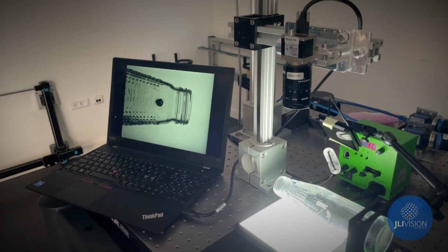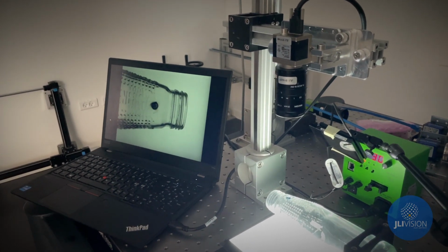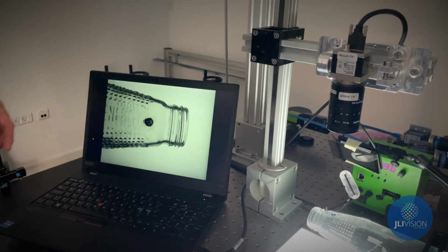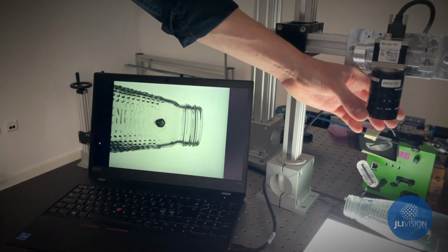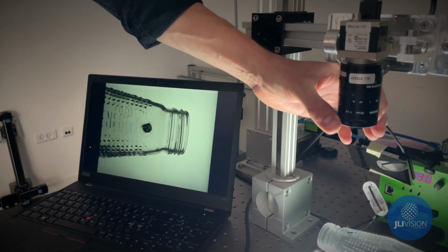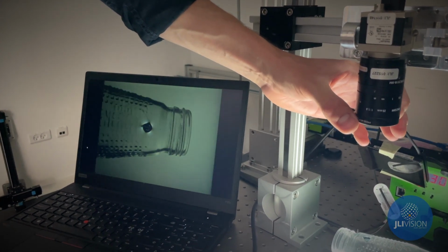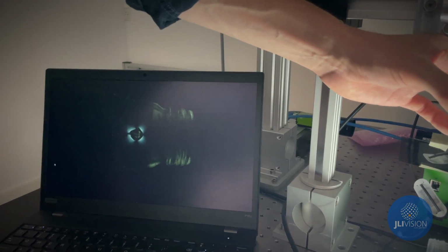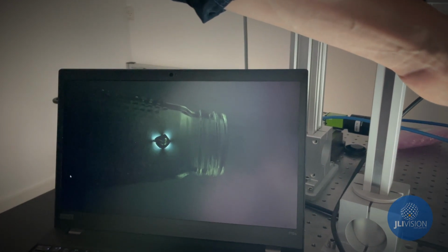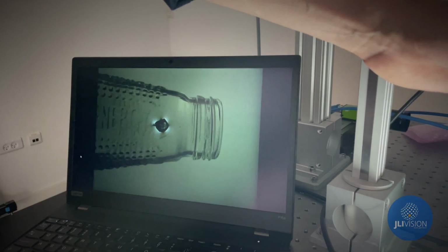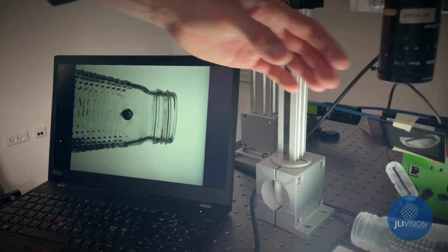A polarization camera can also be used to filter out parts of the light in order to make a specific part of the light stand out. That is the case if we want to inspect glass or plastic for stresses. If you look at a piece of glass with a polarization camera, potential areas of stress where the glass is fragile, that you can't see through a normal camera, will stand out, as these stresses distort the light in a way that we can isolate by filtering out the other parts of the light.